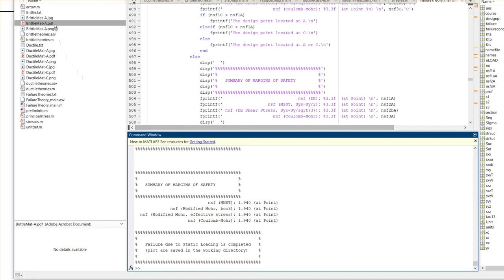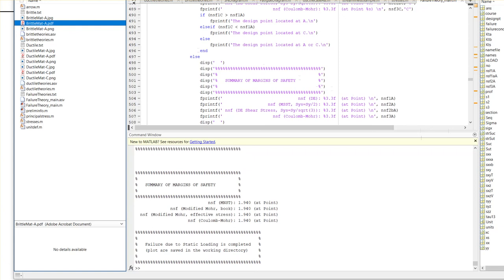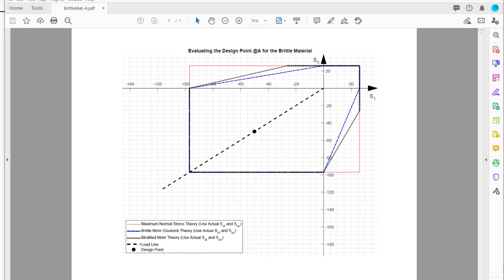Yes. So you run this case, let it run, and you can see that in this particular case, you actually end up being completely compressive. It's negative. So in this location, minus 50, that's where you're at, because all the stresses you have, sigma 1, sigma 2, sigma 3, have identical stress values. And this is the load line that you're working with.